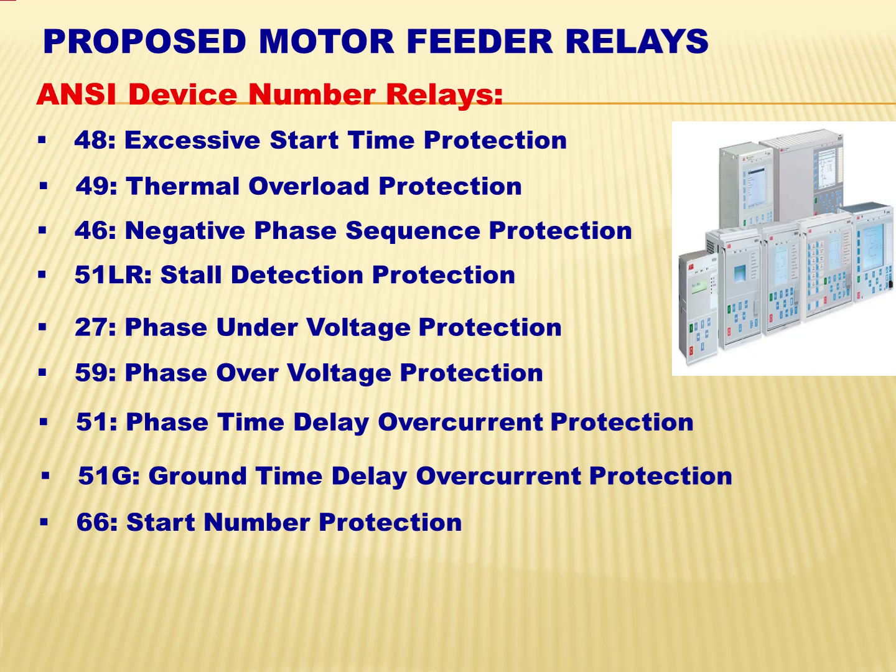Okay, so to ensure that overheating will be avoided due to repeated starting of a motor, a start number protection relay is required, or the relay 66.